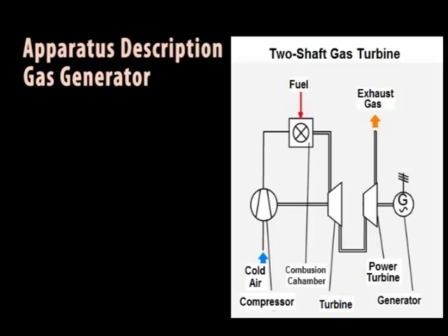At the inlet to the combustion chamber, part of the air is drawn off and fed to the front of the combustion chamber pipe. This primary air is used as combustion air for the fuel. A turbulence generator sets the air in rotation and slows it down such that the fuel is injected in gaseous form via the combustion nozzle and can burn with a stable flame.